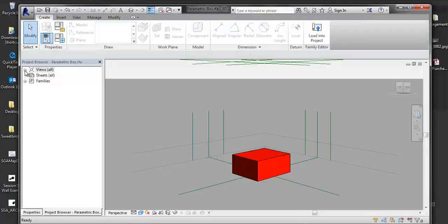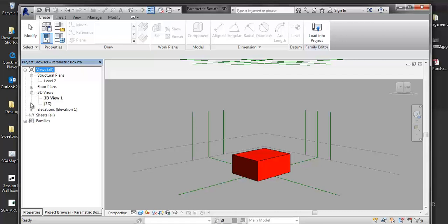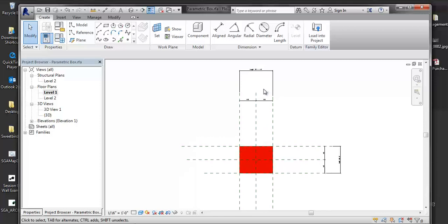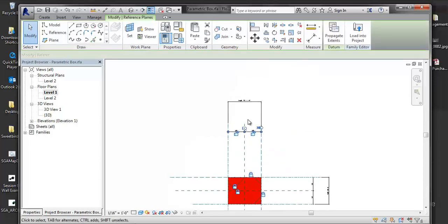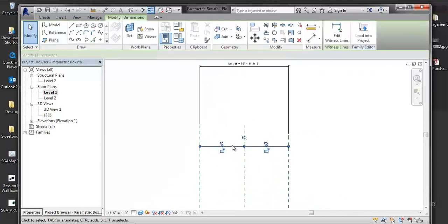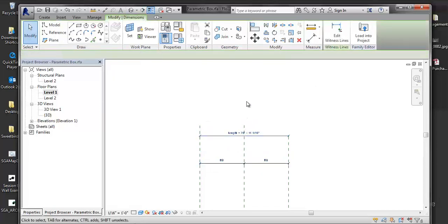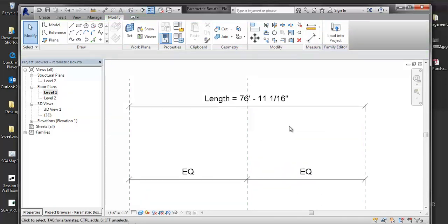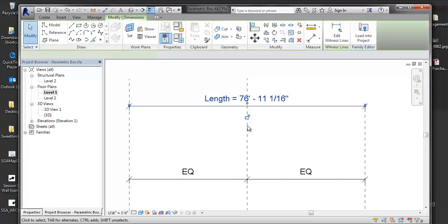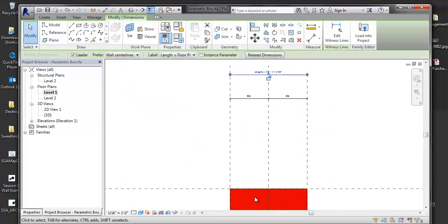What I can do is, this is the massing family. We're going to build the same thing as a generic model. When I look at the floor plan of that, same thing, I see reference planes, but I'm using a dimensional item to push in parametric data. So the dimension drives the reference planes, and then the reference planes host the geometry. So it's that hierarchy structure.